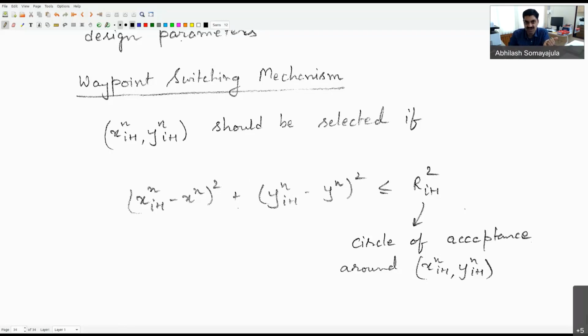So what we have essentially looked at today is that we have put everything we have learned in the guidance systems and the control systems all into one place. We have looked at the idea that the heading controller will take in an inside loop dynamics where the desired heading angle is coming from an LOS guidance scheme, and the inside loop is trying to correct for the error between the desired heading and the actual heading, driving that down to zero using a PID controller.